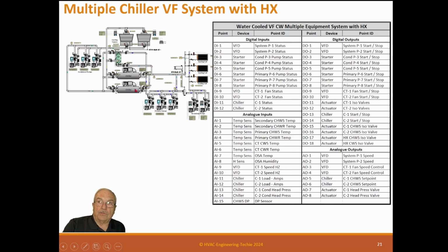If this chiller is the one you want to run the central plant on, then I would use this tower system. If you use this tower system for heat exchanger, then you want to use this tower system to run the chiller, because it'll not have super cold water.